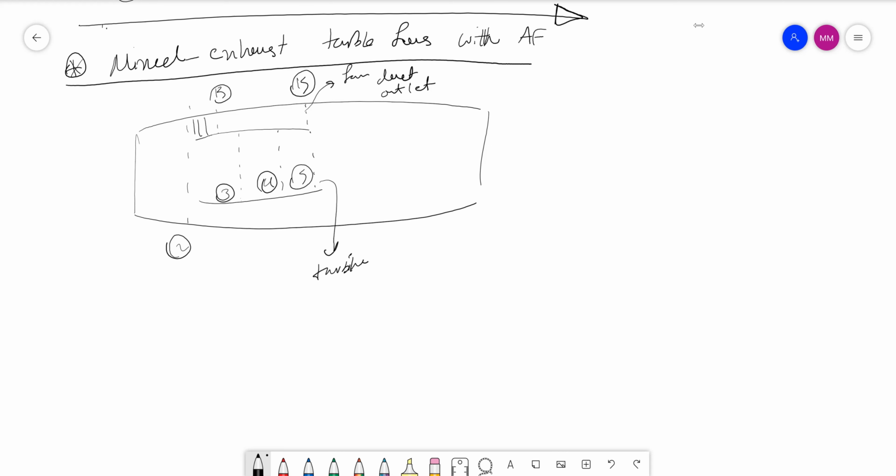Okay. And this new additional part of the turbofan engine is called the mixer, which essentially is a location where the hot gas and the cold gas mix, right? And we call this a station mixer. The station number, the outlet part of it is called 6M. And M here stands for mixer, right?